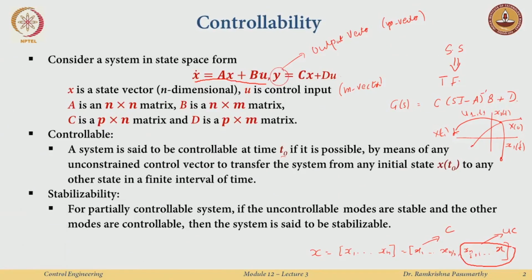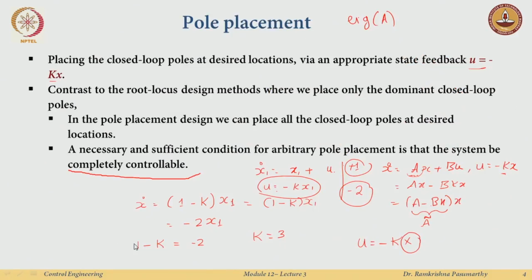Okay, and let's simply assume for the moment that this d is 0. So what is available for measurement is y equal to c times x. And I can ask myself a question: given these measured values, can I get x? Well, you can say that x is c inverse y. This is true when c is invertible, or if the dimension of y is the same as the dimension of x. But usually this is not the case.